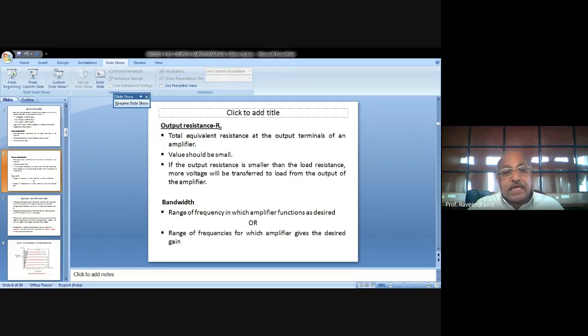The output characteristic of common emitter configuration of the NPN transistor is shown in the graph, which I will show you. This configuration has three regions of operation: the cutoff region, the active region, and the saturation region. And the common emitter configuration can be used as an amplifier when the transistor is operated in its active region of the output characteristics.